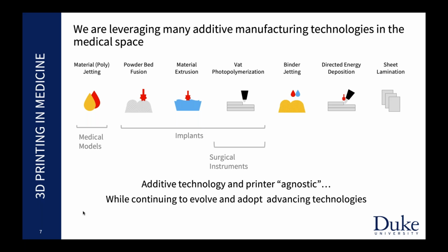You can think of this as a printer that builds a three-dimensional part by ejecting very small droplets of a curable resin. It's not that different from inkjet printing on a piece of paper, where you inkjet these droplets to create the printed page. You just do this in 3 dimensions and build it up. The materials from that are very weak, but they're very colorful and high resolution and have lots of different textures. And so they're very good for models. They're not as good for something that has to bear a lot of structural load.